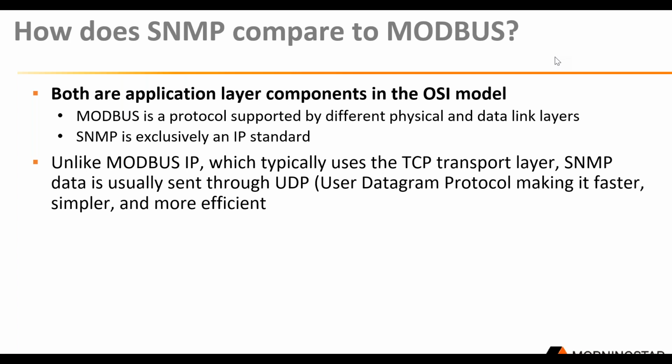It is more of a broadcast as opposed to polling individual devices, and it can talk to multiple devices simultaneously, whereas MODBUS is what they call master-slave is the common implementation, or leader-follower is maybe more appropriate, in that you have to acknowledge a response from each of the follower devices when it is polled by the leader, whereas SNMP can sort of just collect bulk data from a variety of devices that are all connected to the same local area network, and retrieve all the data sort of simultaneously.